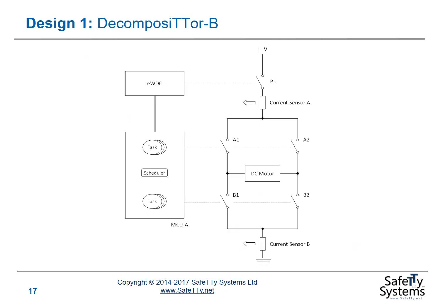Here I want to focus on the high-level decision about the design options. So our first option, and one that is likely to be an obvious option in an automotive space, is to use a single microcontroller, probably in this case an ASIL D microcontroller, and an external watchdog controller chip, and control the system in this way. So we're using ASIL decomposition, two task sets on the same microcontroller, and an external watchdog controller to deal with scenarios in which we detect a failure on MCU A.